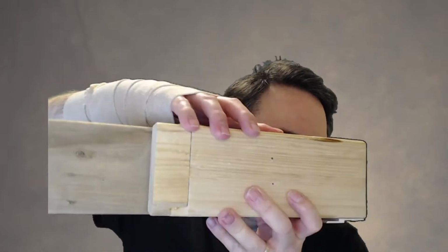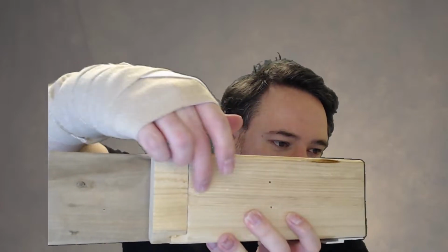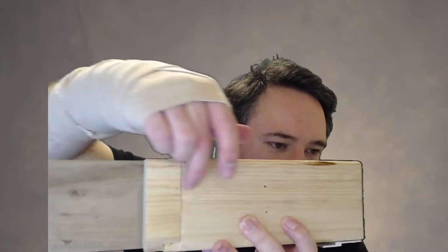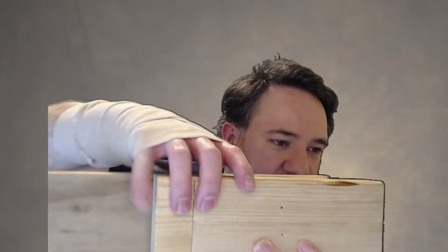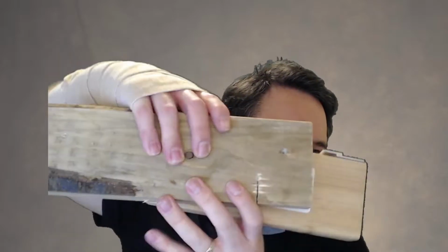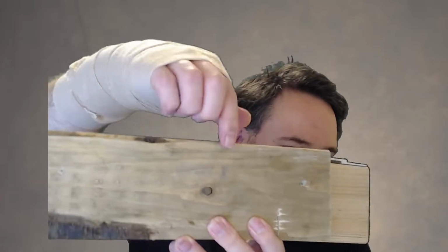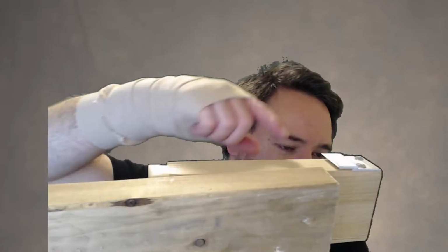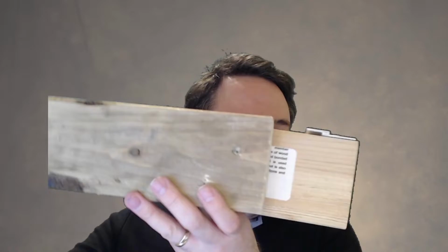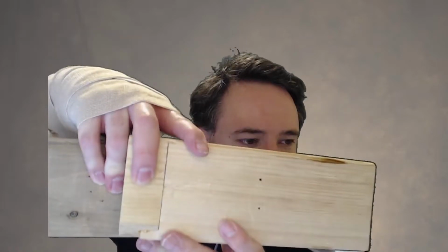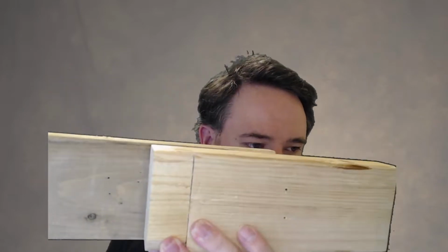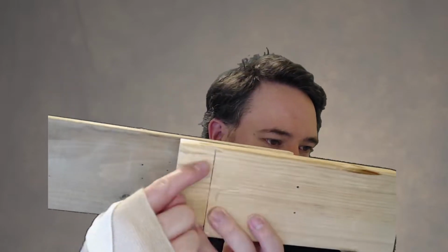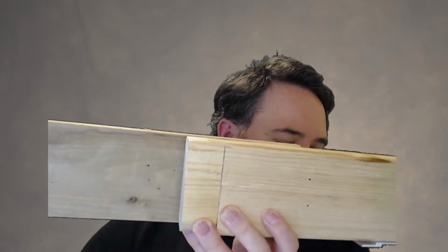Then I'll obviously have to consider an end grain distance here that I don't have to consider in the piece behind because there's no end there. And in the piece of wood behind, I'll have to consider the end on this side, where I don't have to consider it on the front piece because that's not where the end is. Okay, so that's if I have an overlap connection like this. My end distances will be the only thing that is different between these two pieces of wood, depending on how I lay out my nails on that interface.